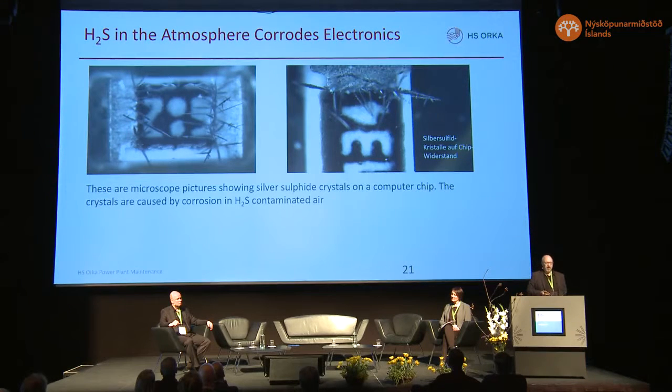Hydrogen sulfide corrodes electronic equipment made of copper and silver and things like that. What we must do is to have all electrical or electronic equipment in compartments where the air has been cleaned and H2S filtered.